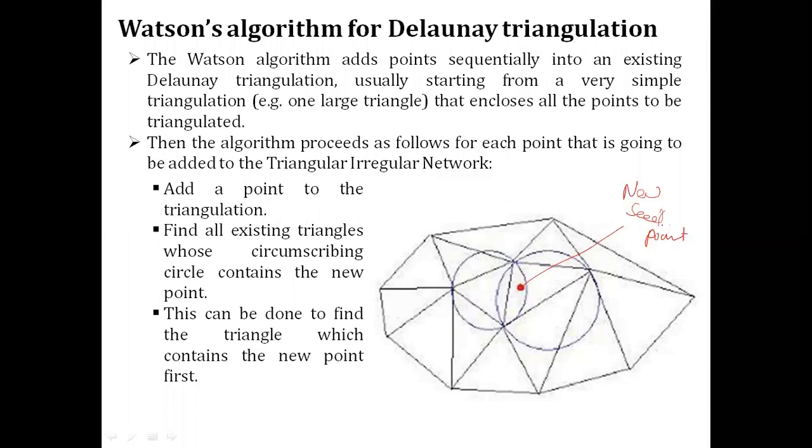If you feel that there is any critical feature on your surface which needs to be finely meshed, you can introduce a seed point in that surface patch also. So the introduction of the seed point becomes a user-defined function, where you can define the seed point as per your own requirement. Now, once you introduce the seed point, you have to check all the triangles which are either adjacent to that seed point or the triangle on which the seed point has been introduced. So once I introduce this seed point, I have to check all the adjacent triangles.